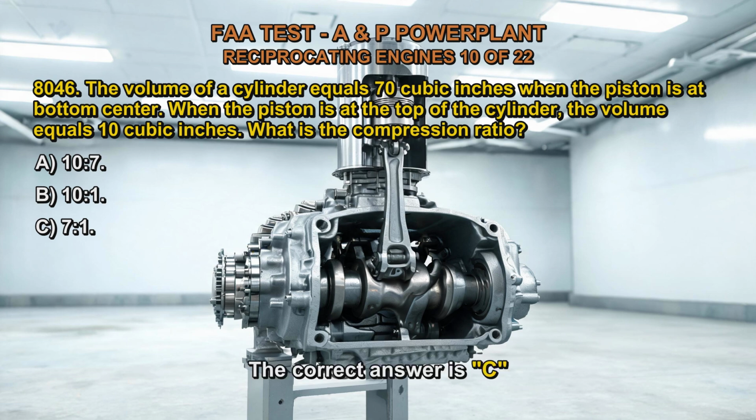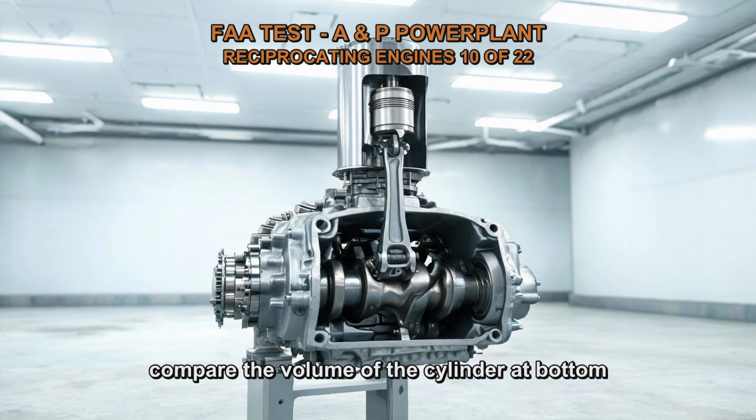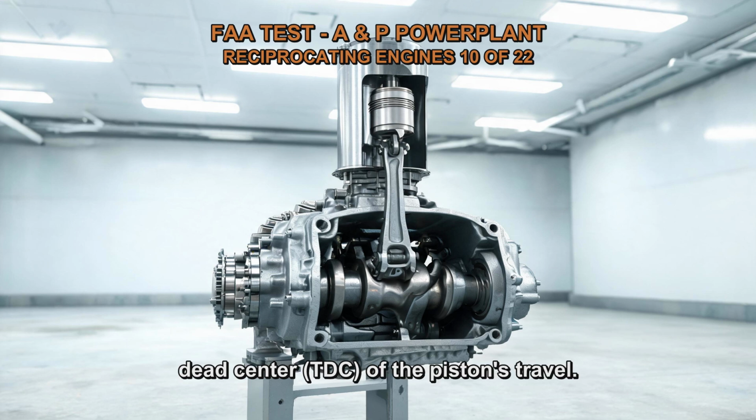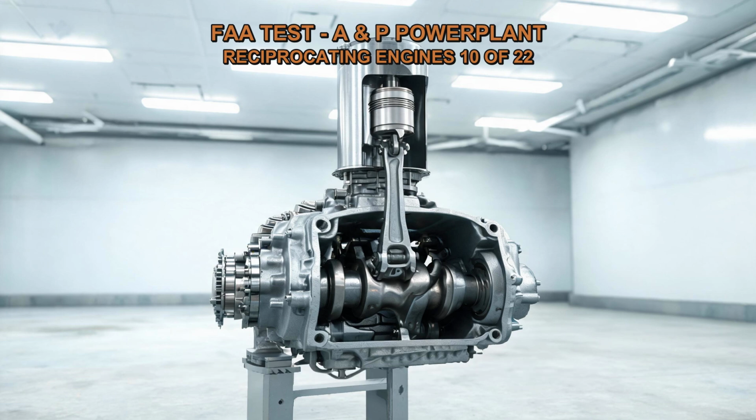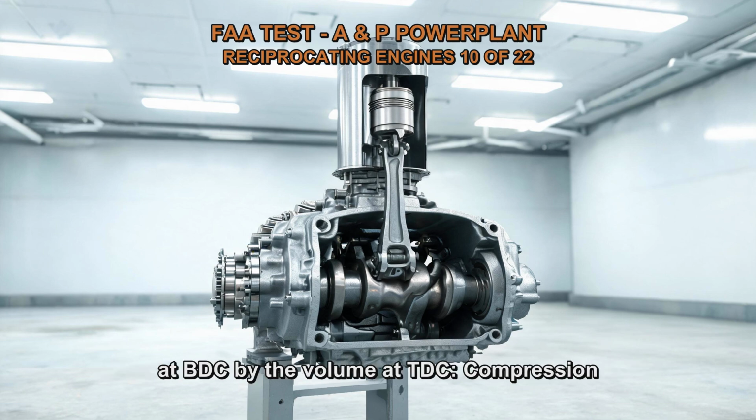The correct answer is C. To calculate the compression ratio, we need to compare the volume of the cylinder at bottom dead center, BDC, to the volume at top dead center, TDC, of the piston's travel. Given volume at BDC equals 70 cubic inches, volume at TDC equals 10 cubic inches, the compression ratio is determined by dividing the volume at BDC by the volume at TDC.